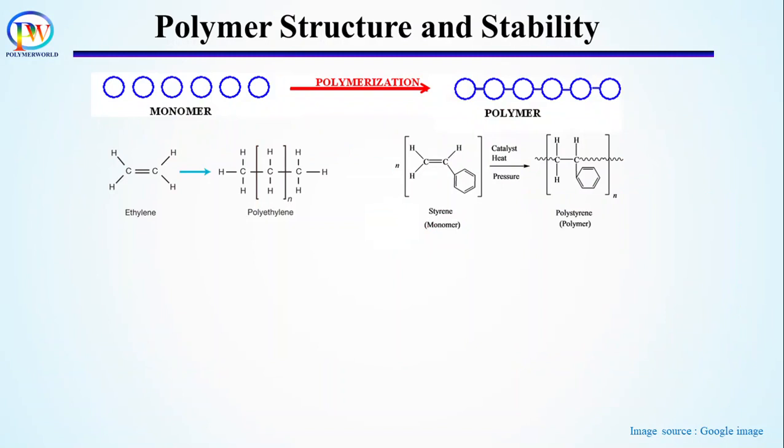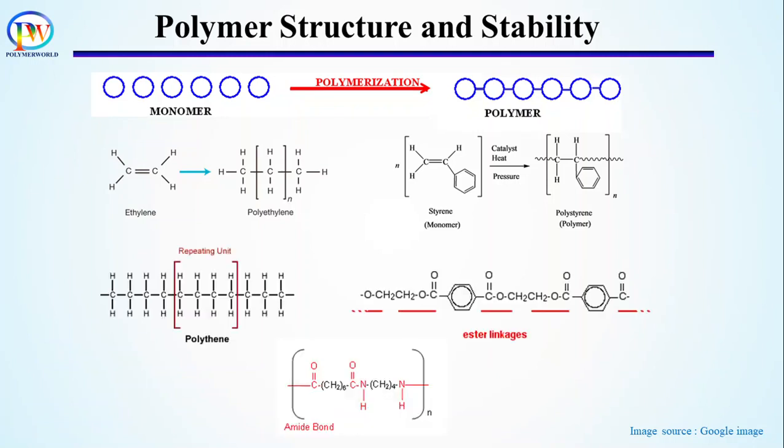We know polymers are formed by joining several monomers like ethylene, propylene, styrene, etc. The monomers in the polymers are mainly connected by carbon-carbon, amide or ester bonds. These bonds are not very strong and in the presence of extreme conditions like high temperature, UV light, oxygen or moisture, these can easily break. Also, except thermoset and rubber, the majority of polymers are used in uncross-linked form so that they can be recycled and processed multiple times. Therefore, the majority of polymers are inherently weak, which makes them susceptible to degradation under extreme conditions.